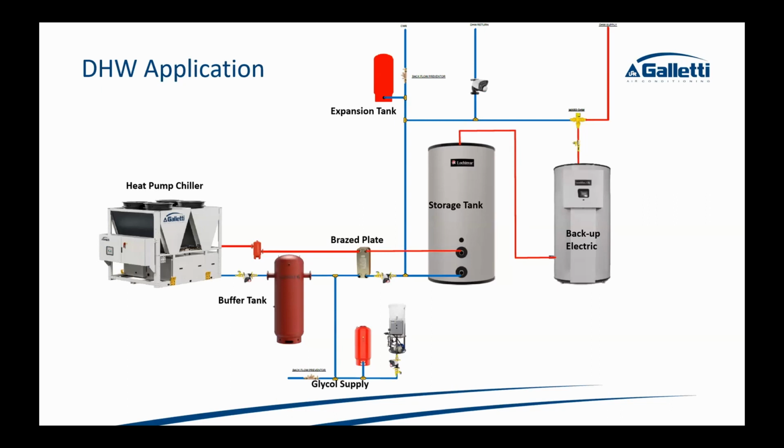Now, CO2 units require a very large differential on their water side. That's why a lot of times you'll see promotions for, okay, we can store at 180 degrees. The reason is that if you have a return water temperature that exceeds even 70 degrees, a lot of times that'll actually kick off the CO2 units. They go off on a high inlet water temperature alarm. So just keep in mind that depending on the refrigerant, it may impact your piping design and your entire system sequence. There are other things to discuss about CO2, but with regards to piping, that would be the big consideration.